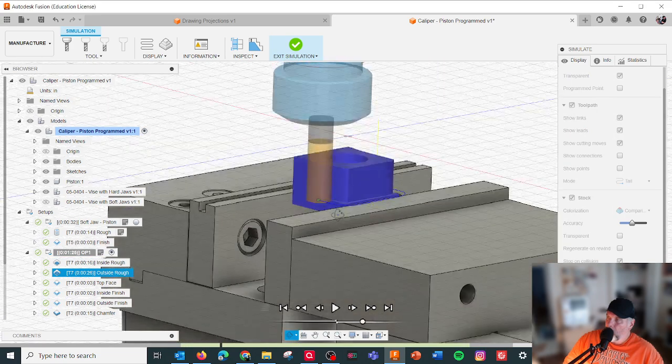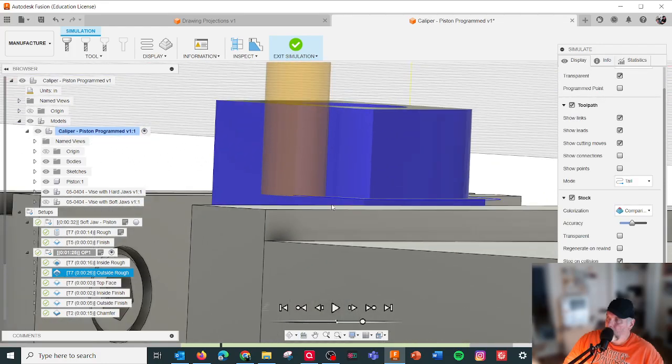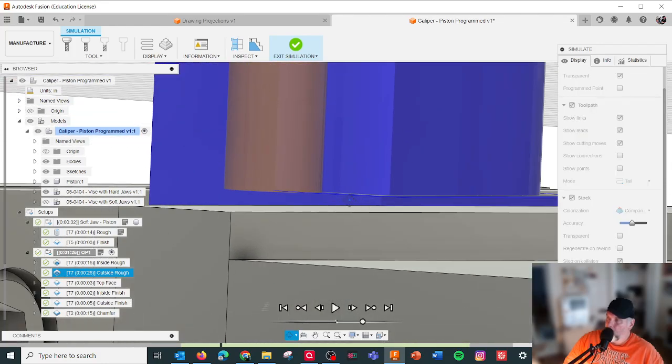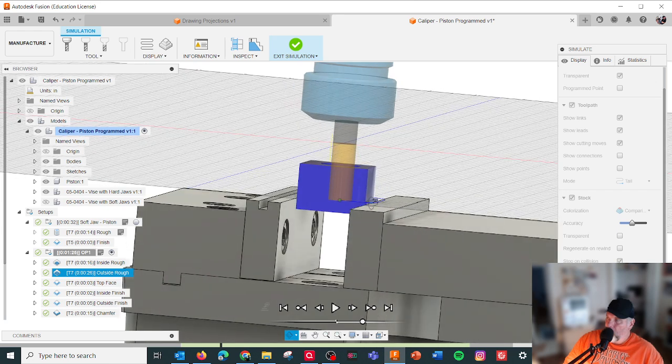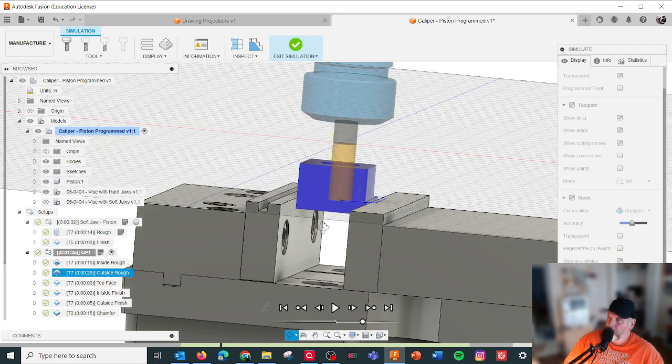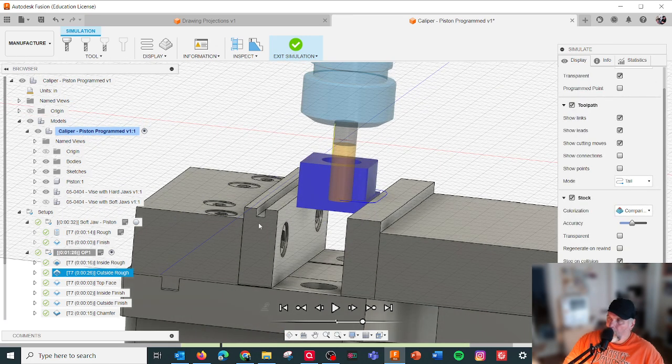And when I go around the outside, I can bring it up and say, this is what we want to make sure we don't have. This is set up to use parallels. I do not see the parallels in there, but personally, we make jaws that are cut 200 thou deep by 200. We do a notch. We make steel jaws with notches in them. We don't use the hard jaws with parallels because it guarantees the setup will work every time and the parallels don't flop down. I do have a set that I can bring in and swap into this setup, but this is your standard Kurt vise.